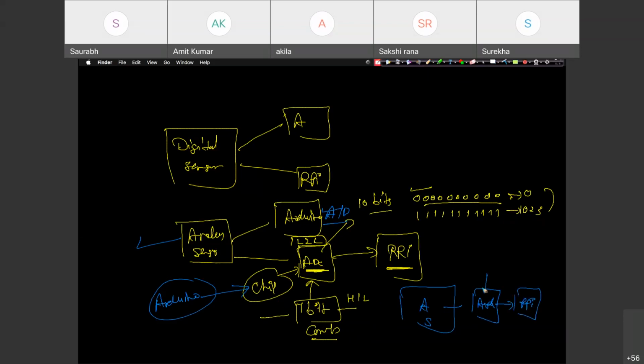And here, your data will be coming from the sensor in analog form. You have to write a program in embedded C language. You will convert your analog data into digital using embedded C, and now you will communicate that data. That data would be in the form of values from 0 to 1023. So you will send this value from Arduino to Raspberry Pi.